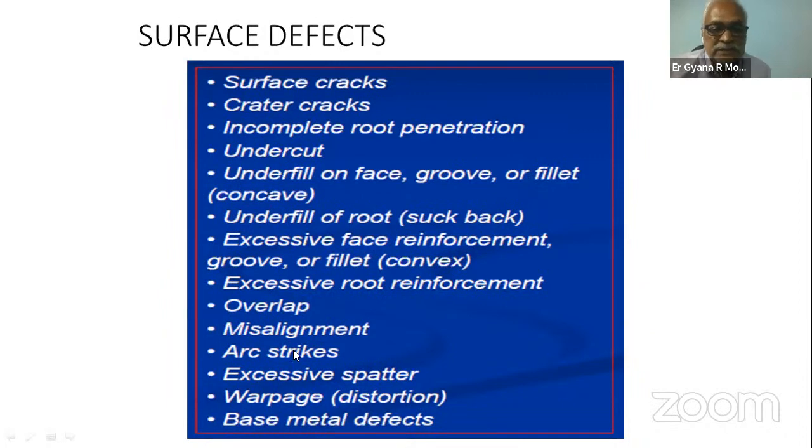Then arc strikes. You know what happens normally when we are doing welding, let us say with a stick welding rod. To test whether the welding rod and welding machine are working, the welder keeps on touching the components. So these are all arc strikes.